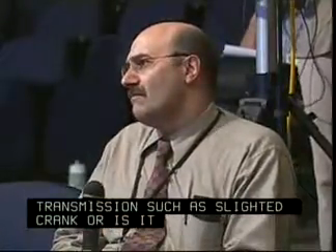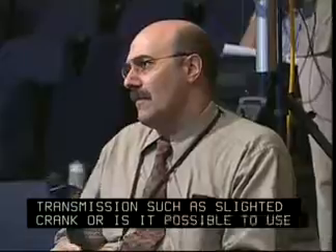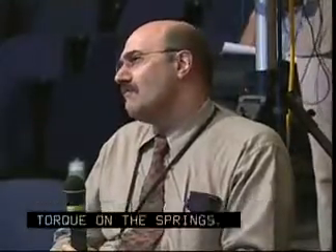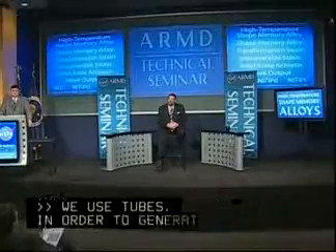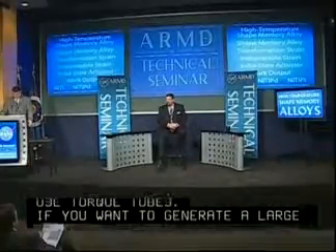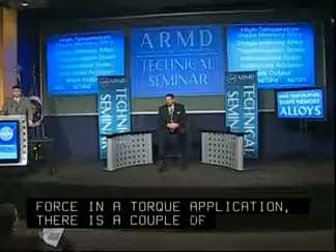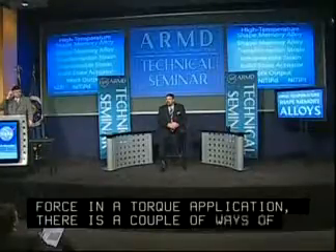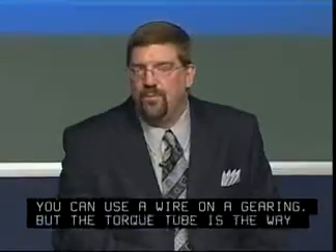Actually, we use tubes. In order to generate a torque, we use torque tubes. So if you wanted to generate a large force in some type of a torque application, there's a couple ways of doing it, but the straightforward way is to use a torque tube. The other is that you could use a wire acting on some type of gearing, but the torque tube is the way to generate the high forces.